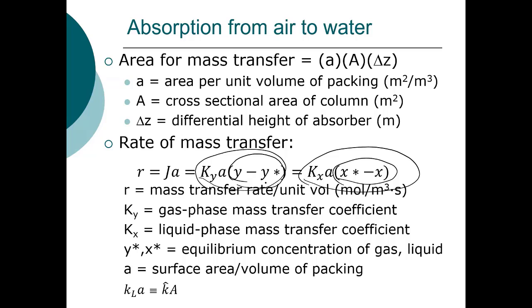The greater the difference, the greater the mass transfer. So for instance, let's think about oxygen. Oxygen is more soluble at lower temperatures. So that equilibrium concentration is greater at lower temperatures. So I'm going to have a greater mass transfer rate of oxygen at lower temperature than I would at warmer temperatures.